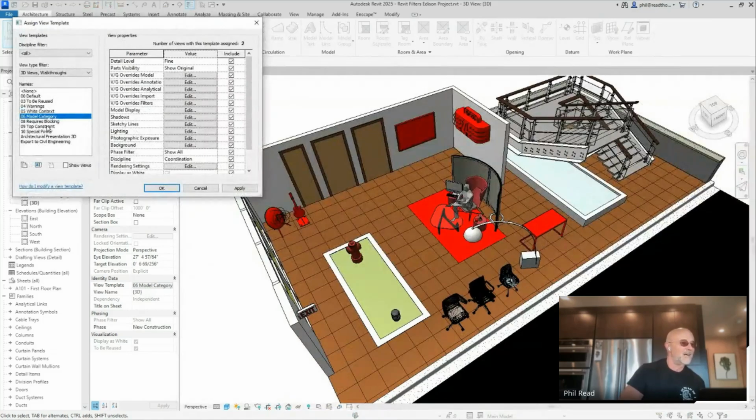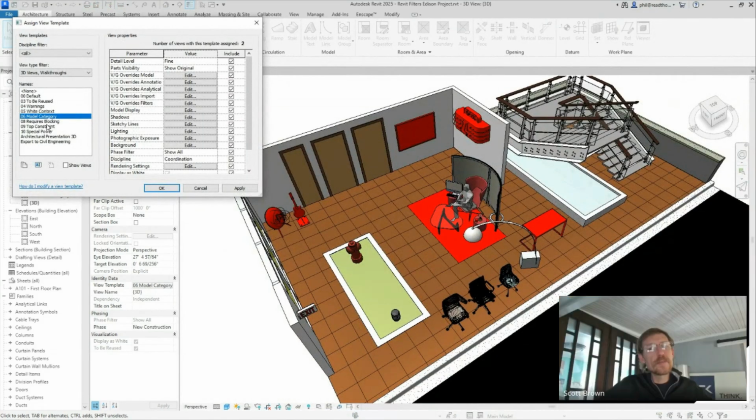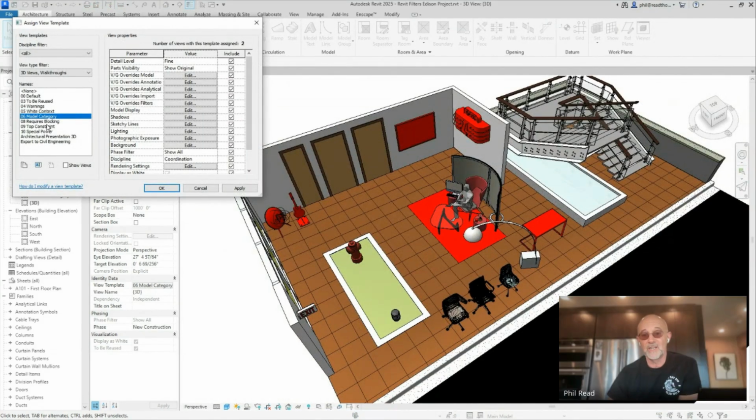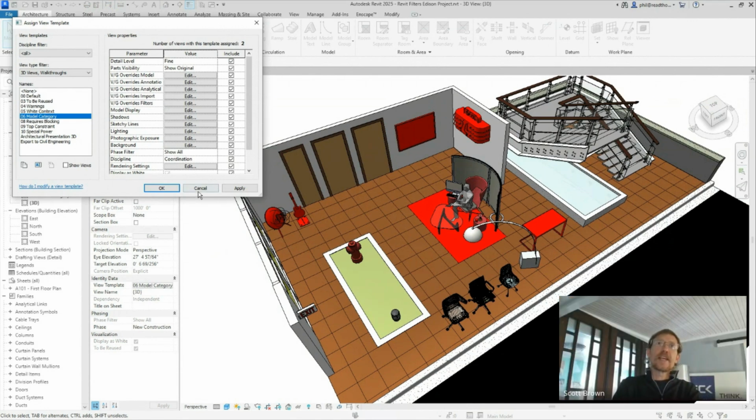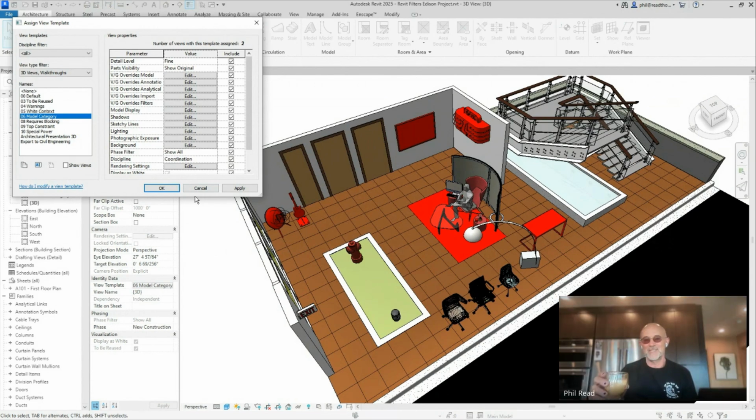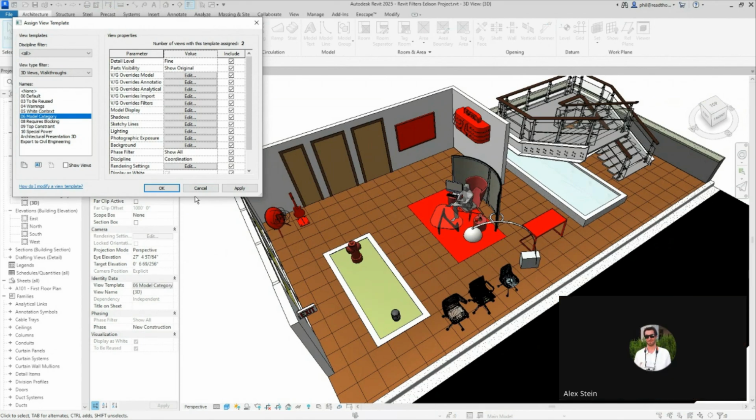Have you figured out you can do a filter to find in-place families? Is that one that you don't want in-place families? We don't want in-place families, but they can be of any category, so I'm not sure we can filter that right now. Filter for in-place families is almost like a religious discussion, because some people go, "Oh, I have to have an in-place family sometimes." Right. We can run a script that updates a parameter and filter by that, but it would require something else to be run.